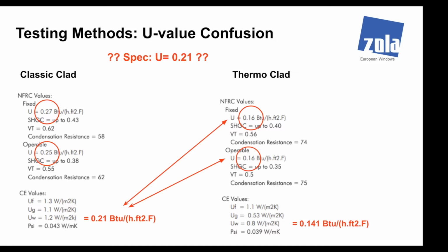Now in the Passive House realm, dual glaze is not appropriate for the Northeast, especially New York City, when it comes to performance. But what we're seeing is passive measures and people trying to just build better right off the bat, trying to hit New York City thresholds for increased performance. That points them to looking at values, but if you're shopping European windows and converting the BTUs that they give you, then you're going to get a value that is out of alignment with what you're going to need to submit to the New York City DOB for code approval.